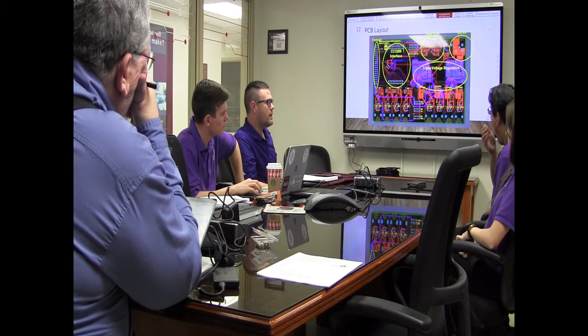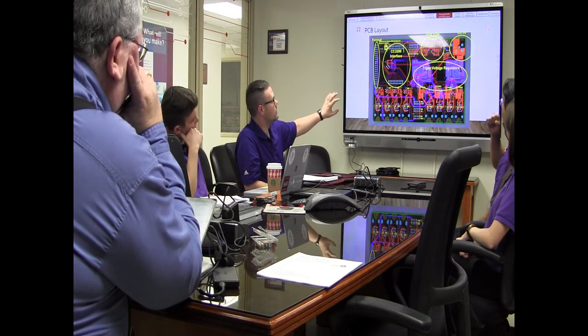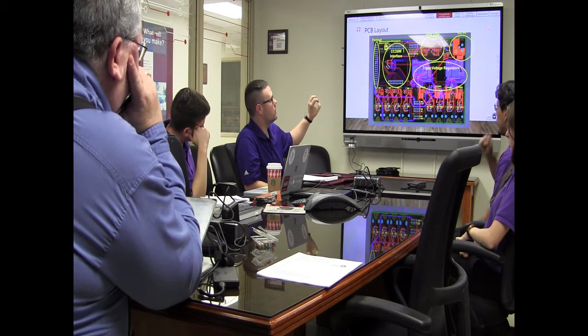And how do you have them stacked right now? We have it stacked, so if you look through the board to where all the blue layers are, that's the back of the board, and that's where all of our voltage regulators are. They're producing the most amount of heat, so we put them underneath the board, as far away from the temperature sensor, which sits on top of the board.